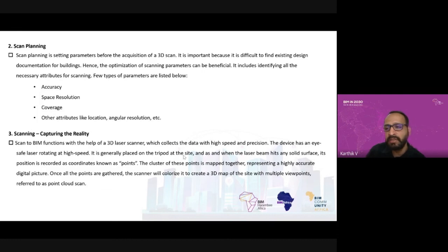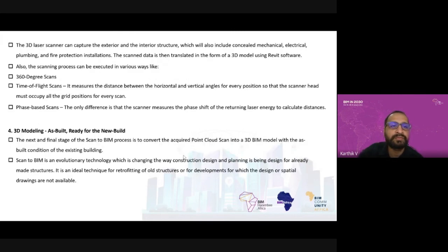It will capture all the non-moving objects. Sometimes it will capture moving objects. So a few times we scan in the same location. If an object is appearing and disappearing, it is just removed from the scan. So it will be easy to clean up the unnecessary information before we compare with the actual 3D model.